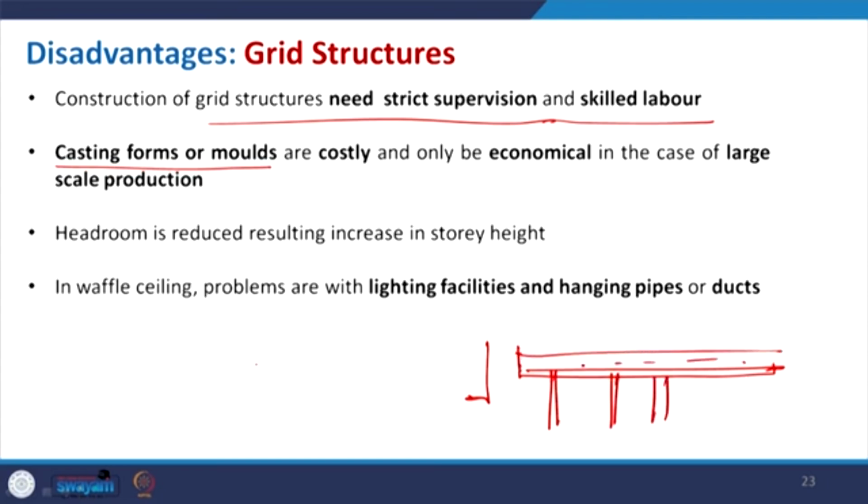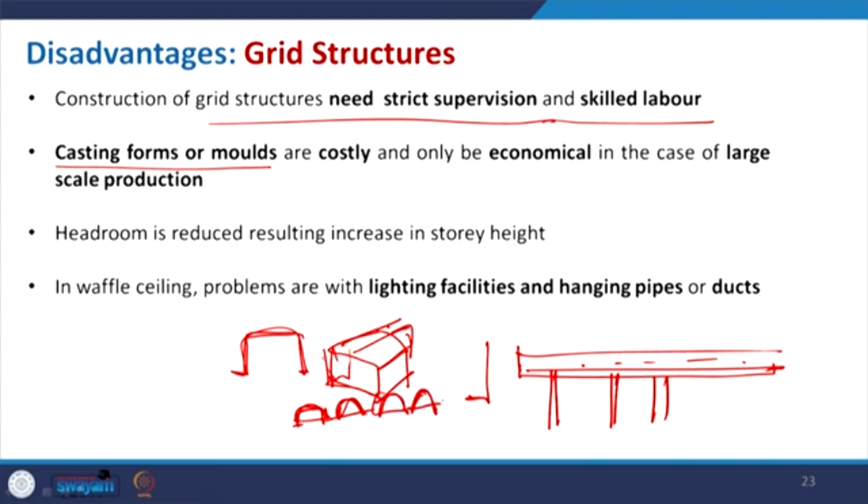But for this we need some mold, which basically looks like this, and we place one after another and then we put the reinforcement on top of it and we fill it. So, basically if we try to convert this, your formwork now looks like this. All these molds will be placed one after another and then we cast.